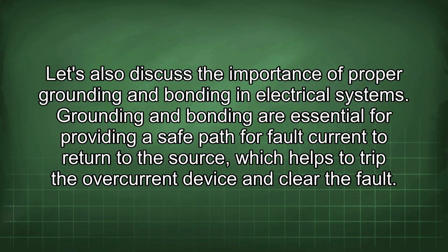Let's also discuss the importance of proper grounding and bonding in electrical systems. Grounding and bonding are essential for providing a safe path for fault current to return to the source, which helps to trip the overcurrent device and clear the fault.